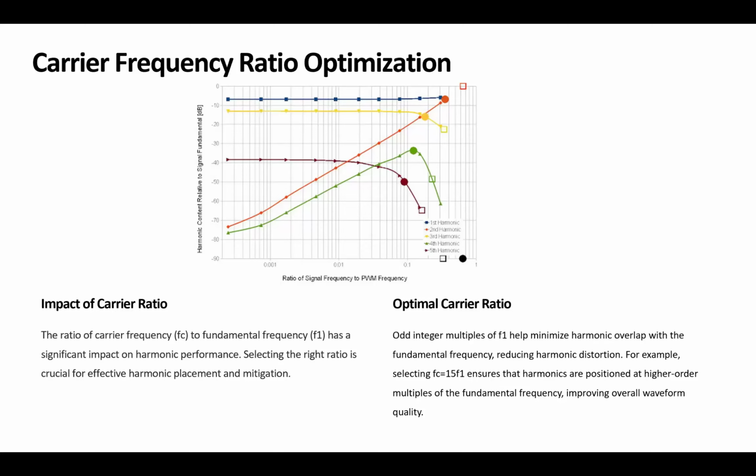Okay, we can suppress or mitigate harmonics. Now we had two strategies. Either we could optimize it to minimize the total harmonic distortion so we don't target a specific frequency. We try to generally minimize the harmonics.